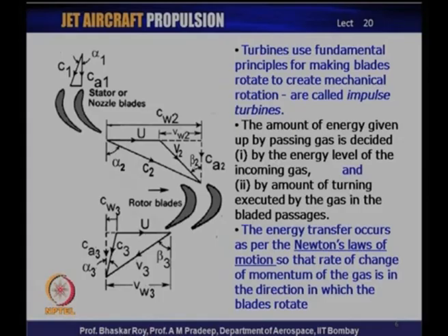On the other hand, the relative exit Mach number from the rotor, that is M3 relative corresponding to V3, is going to be a little less than 1, deliberately kept subsonic, essentially to avoid shock-related issues. The moment you allow the flow to go sonic, you are likely to have shocks around the blades.